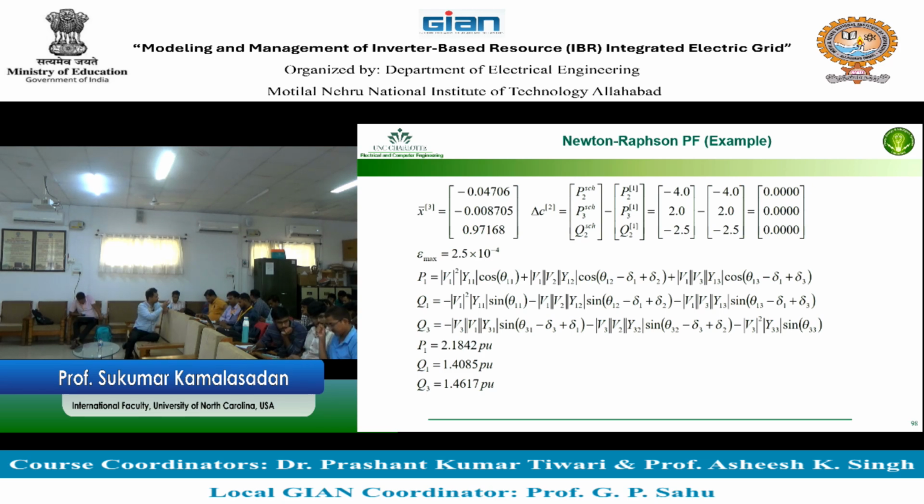When you run, then you get P and Q from the substation for the distribution network, the 2-bus system, not the last load, S load 3 or S load 2. Calculate the S load on the substation. Take that number, multiply with a scale, 10 times or something, to match the load on the transmission on the second bus. The second bus load is 100 MVA, whatever; match it close to 99.9 or whatever that number is, multiply by that, and then run the transmission one again.